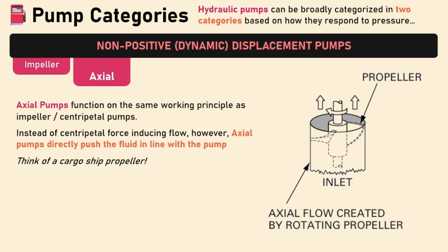It has to be primed, right? Obviously, if I just set this on top of some kind of fluid, if I literally just put this on top of a cup of water, this isn't going to pump anything, right? It either has to be fully submerged or it initially has to be filled up, but it cannot start with just air, right? We have to prime this. And it also experiences the same outlet pressure response, where if on the outlet side pressure builds too high, the propeller will no longer be able to spin, and the fluid might flow backwards.